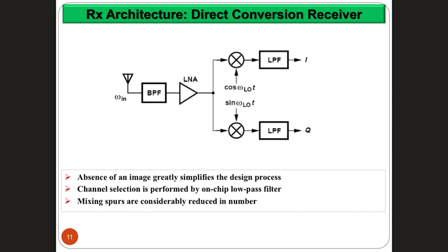Also, in many cases the direct conversion requires oscillators with very high frequency, which is quite difficult to implement, both in the transmitter and the receiver, in older technology and maintain it with small size within a chip. With newer technologies and with better silicon capabilities, now we can have oscillators and mixers with very high frequency operational capabilities, and they can still be integrated inside the chip. So with the advancement of the RF chip technology, the direct conversion became a possibility or something good.